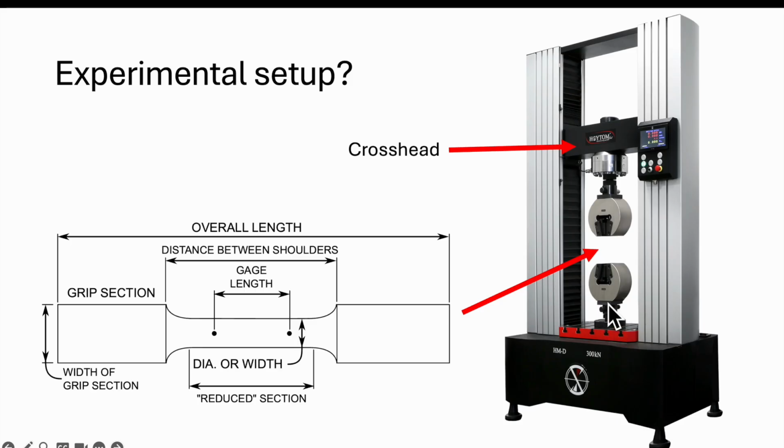So typically the grips are attached to the base here by junctions up here to the load cell and so forth. So all of that stuff can get displaced. And so that's all collectively adding to a displacement, meaning that the strain is also going up. So that strain is going to be bigger than the extensometer strain.